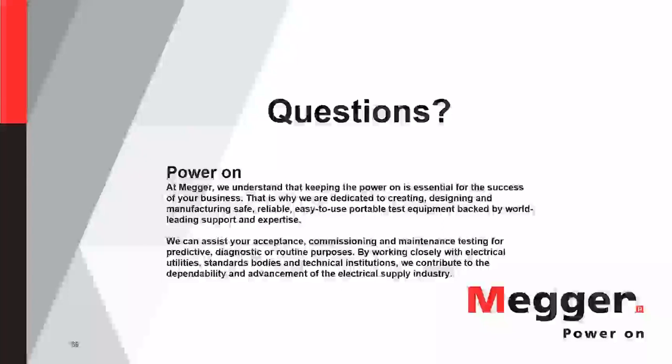No, and as I said, what I recommend from what we've seen is if no information is given, you want to go right at contact separation, is where that arcing zone starts. So as those contacts separate, now there's no more direct connection, so you're going to have an arc going on inside that circuit breaker. So then you just go from there, and the reason we use 10 milliseconds is just